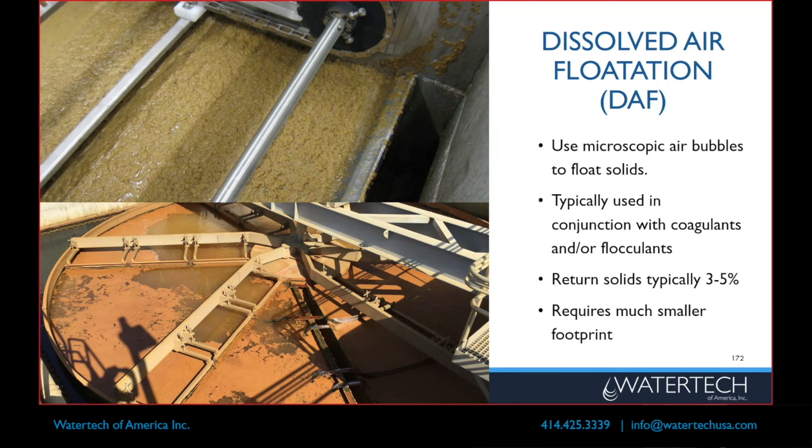Much smaller footprint, higher cost of treatment because you have the recirculation system on the DAF. That's typically a higher pressure pump, compressed air. Compressed air is not cheap to generate, and then some type of coagulant or flocculant, so a chemical cost that goes with it. DAF is great technology, but it's not the cheapest technology.